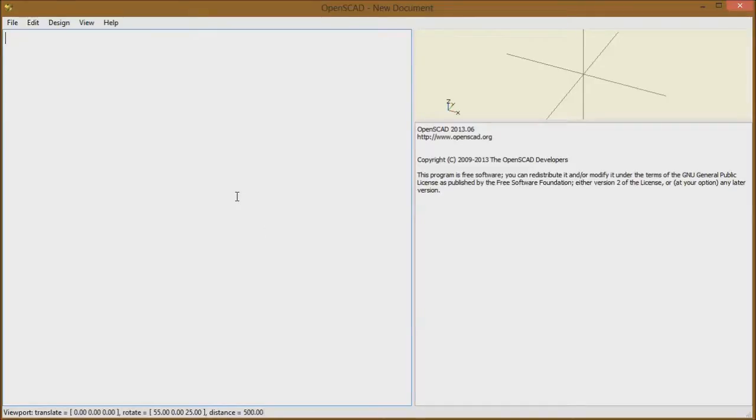So one thing with OpenScad that's very, very useful for me, that almost makes it the ideal tool, is the fact that you can parameterize your work. So what that means is you can specify a couple of parameters up front, and if you then build your tool based on those parameters as opposed to hard-coded values, you could very easily vary the size and the design of your model after you've done all the hard work to make it all fit in.